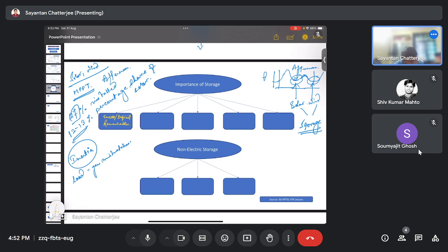Now, another mode of operation that we can see is islanded. Batteries can help during islanded operation. During the islanded mode of operation, the grid is absent, right? So when the grid is absent, the entire power generated within that island has to be consumed, and vice versa, the amount of load required within that geographical location, within that microgrid, has to be met by the renewables in place.